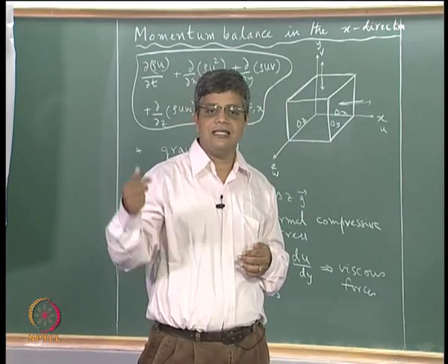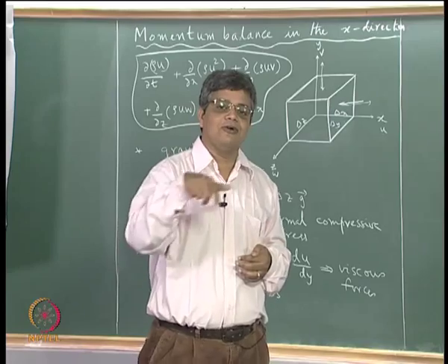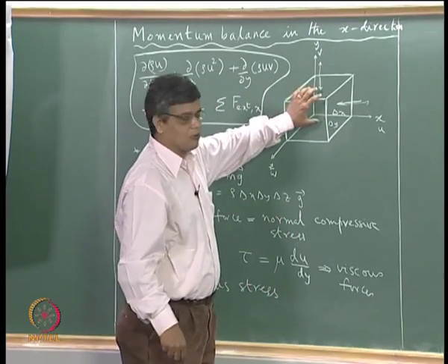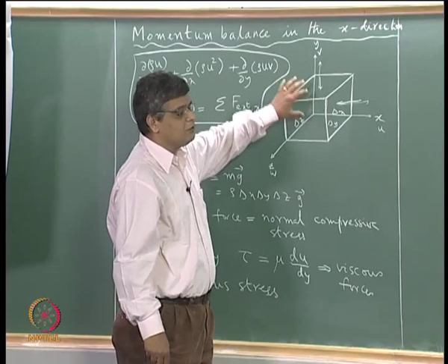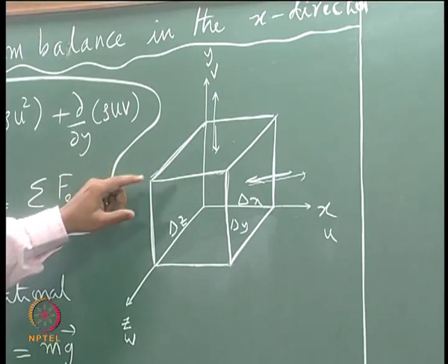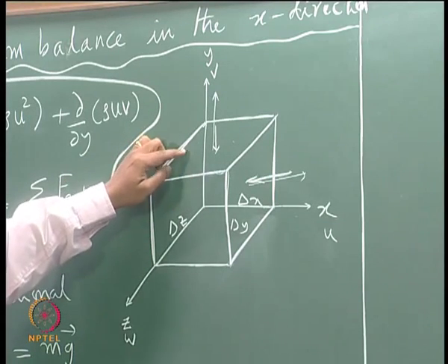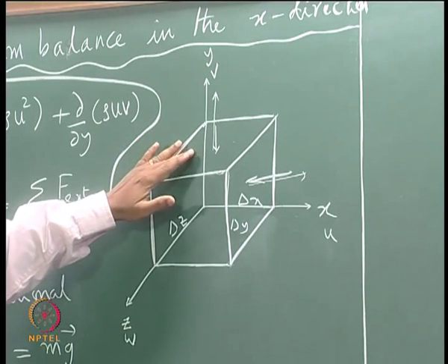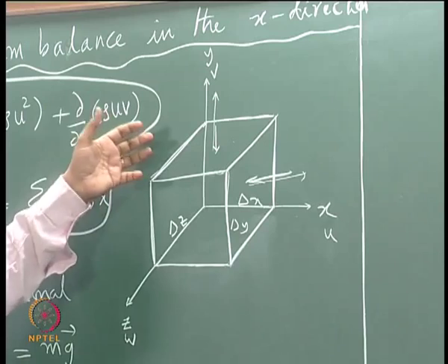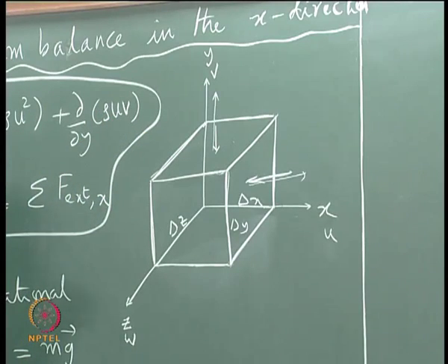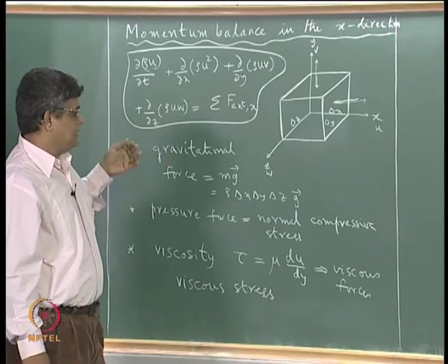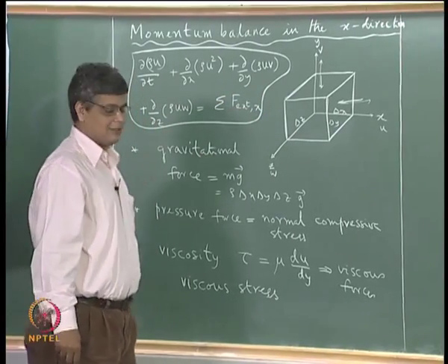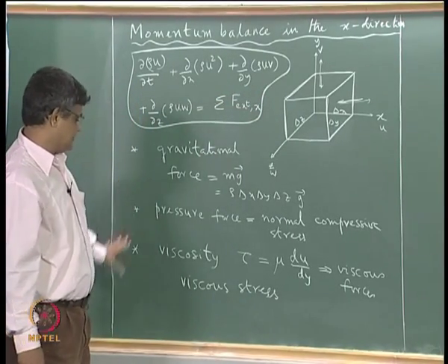It is not in the interior of the fluid continuum, and we are talking about a fluid control volume which is everywhere within the fluid continuum. So unless you have an air liquid interface at this point or within this control volume, we need not consider surface tension. So surface tension would come up as a boundary condition rather than as a force within these considerations.